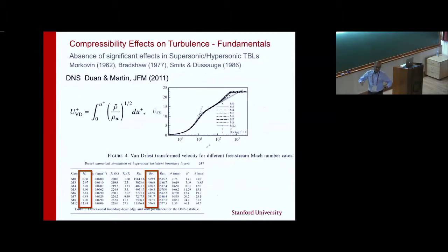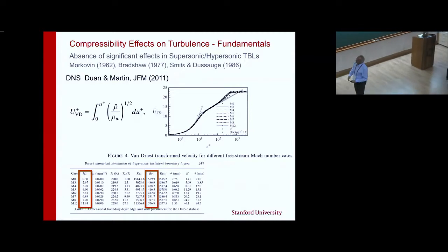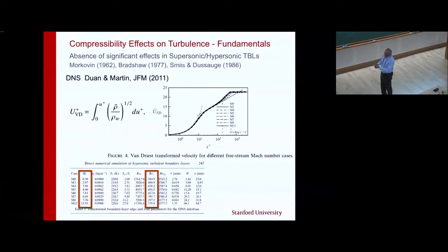So we'll complete the fundamental picture and not worry about more recent results. This is the contrast to compressible shear layers, and the Van Driest transformation is collapsing velocity profiles from incompressible to Mach 12 boundary layer flows onto essentially the same curve. And so this is the variable density effect that, in an adiabatic wall boundary layer, is explaining all the velocity profiles. And a similar explanation for the turbulent fluctuations is also available.